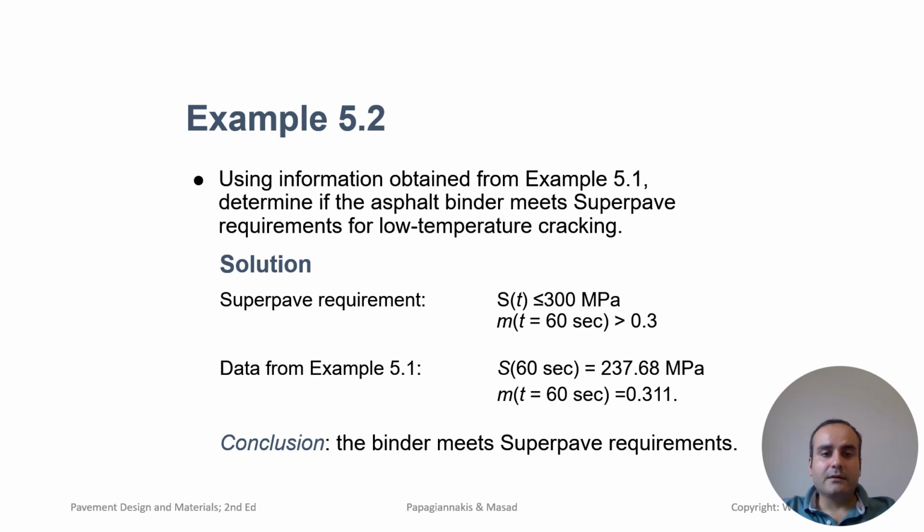0.3. Using the data from example 5.1, the stiffness value was obtained as 237.68 megapascal and the m value was obtained as 0.311. So based on these values, the binder meets Superpave requirements.